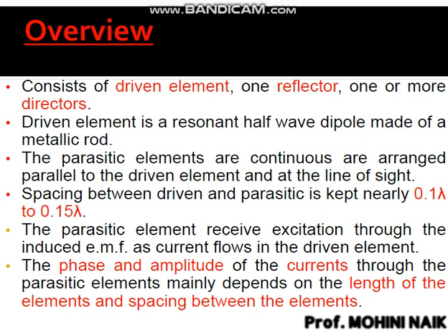As a designer, I will have an option. I can keep the distance between these parasitic and the driven elements anywhere from 0.1 multiplied by lambda to 0.15 multiplied by lambda, and there is a lot of analysis to be done over here. Suppose I take 0.1 lambda, and also there is case 2 where I will take 0.12 lambda. There will be a third case where I will take 0.14 lambda.